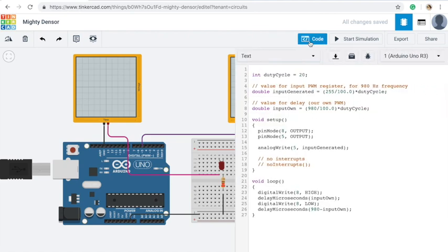In the case of hardware PWM, we cannot change the frequency. That is something that we can do in software PWM, but it is only easy if there is no other code in the main loop. If there is code in the main loop, we have to be aware of it, know the exact time of every operation done there, and account for it.